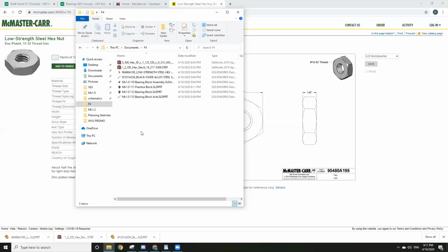Boom. What I don't want to be doing is call this 6-inch axle, because that's something that might change in the future. Maybe I'm not going to make it 6 inches. Maybe I'm going to make it 5.999, or something of more value. But you don't want to put dimensions in here, just descriptions or names of what they are. And then use this numerical naming system.